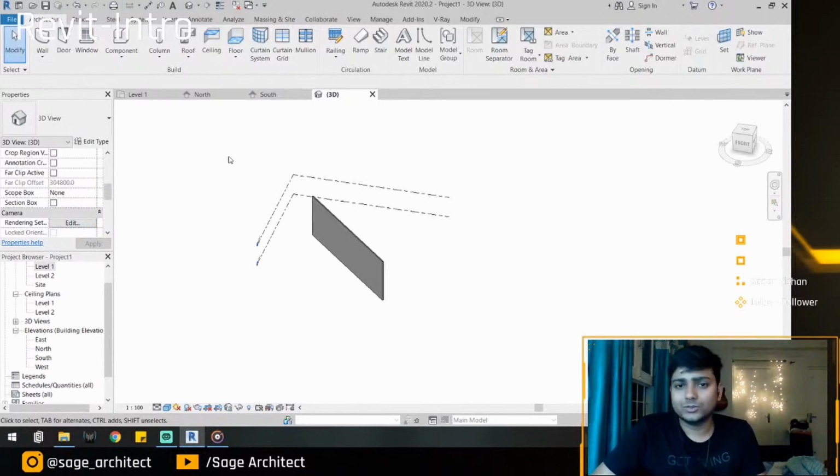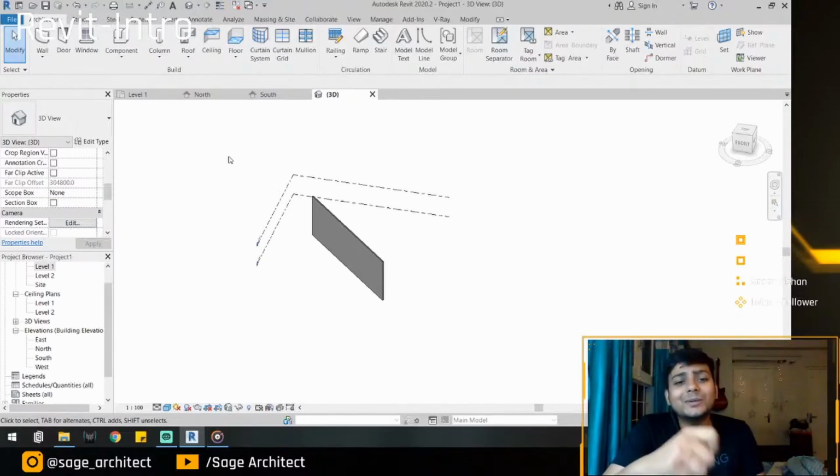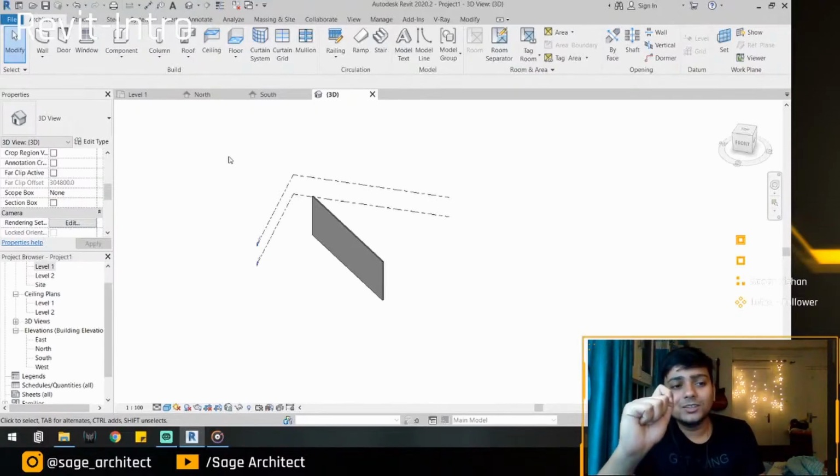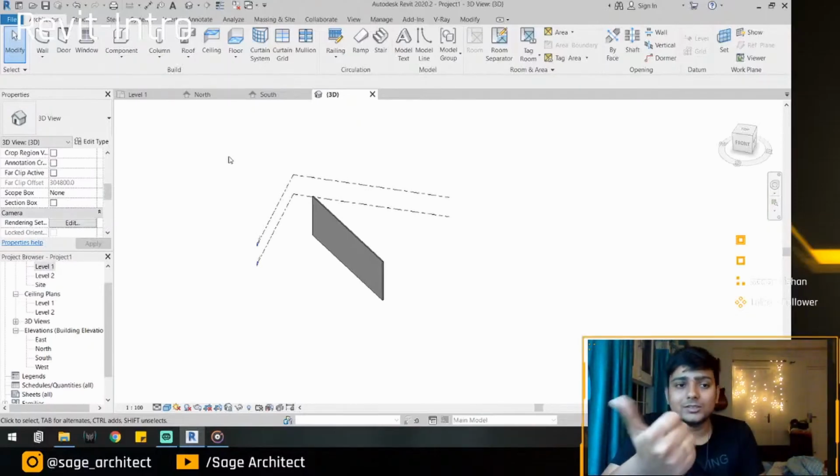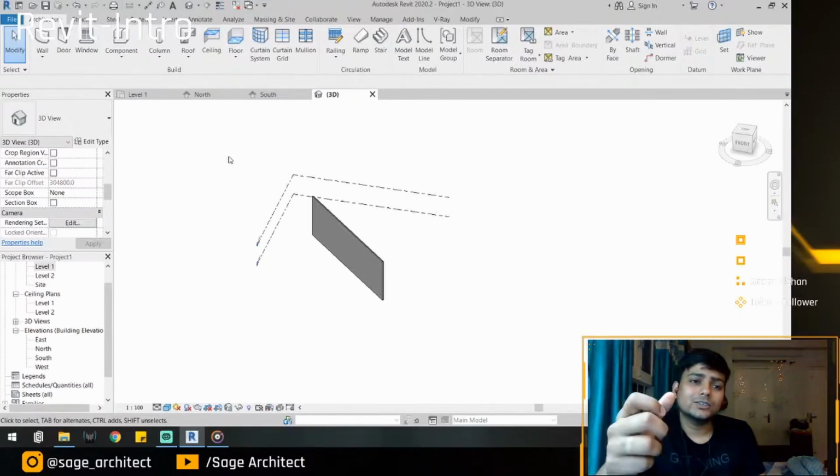But you can make a model on an i3 also, or on an i5 also. You can make an entire apartment on an i5. You have to know the tips and tricks, so you can make the model as light as possible while doing what you want to do in it. Like you can create links, groups, and components, and copy them, so the project weight is lighter. So it is possible.